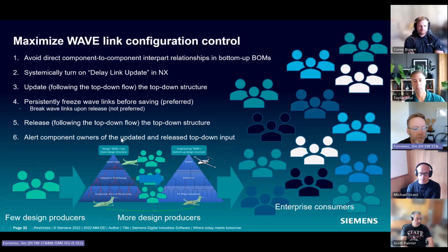Alert component owners of the updated and released top-down structures. In other words, if you own the top of this top-down structure and you've updated it to a new primary geometry, you've gone through the levels and you release them, at that point in time, let the owners of the stuff below know that, okay, we're ready to go. You guys can update to these parts, right?